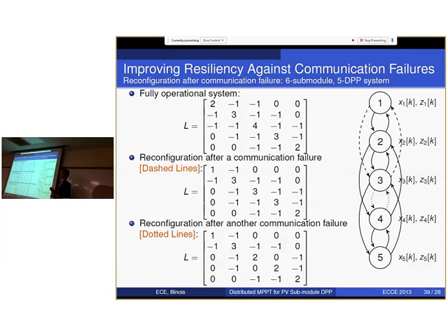So you just need to change your update function accordingly. You don't need to make any change in hardware configuration. Just change within software. This matrix is actually distributed in all converters. Each converter only needs the part that concerns itself, so converter 1 and converter 3 can locally change their own L without making changes to any of the other converters.